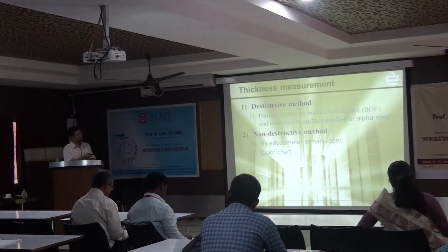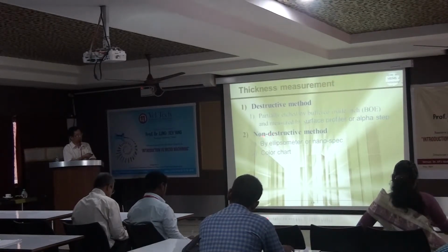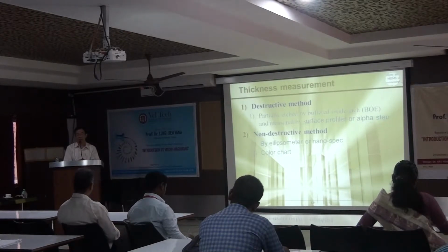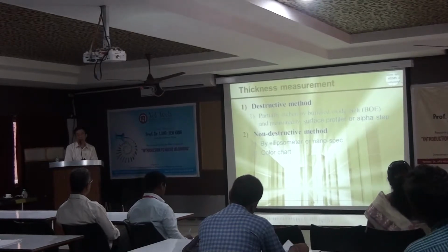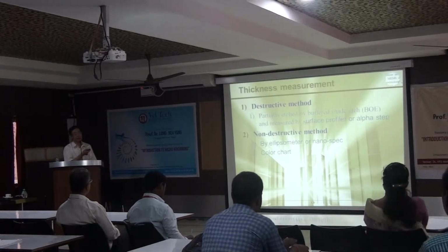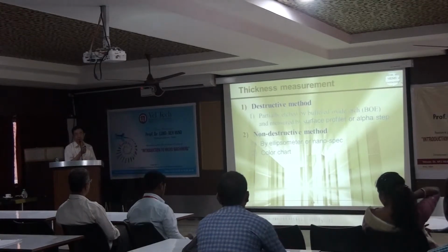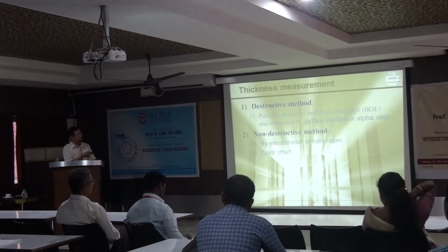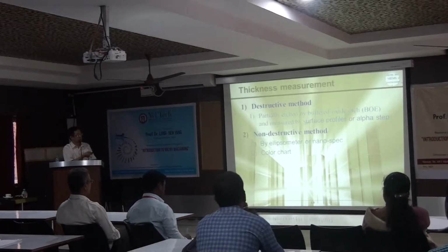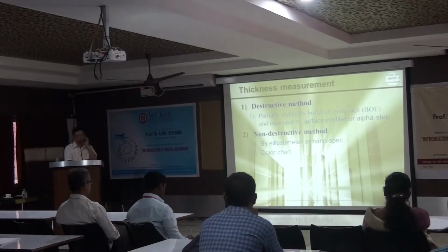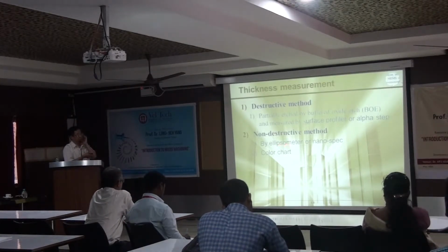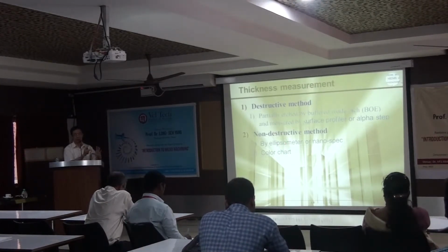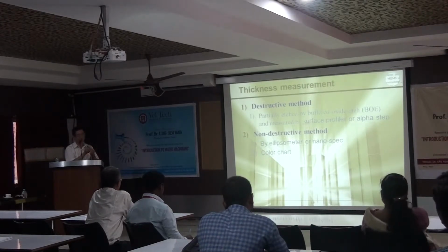If you want to keep the function of your wafer, you had better use the non-destructive way, NDT. It means that we use optical measurement to detect the thickness. You can use an ellipsometer or a nanospec. These two kinds of machine measure the thickness of oxide. The ellipsometer needs a laser to help you to measure.